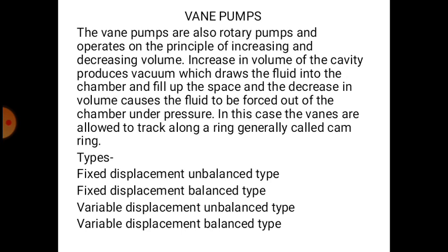So in gear pump, as the gears are unmeshing, at that time volume increases, and at the inlet side unmeshing is going to happen and it is going to suck the oil inside it, and at the exit port the gears are meshing and volume is decreasing, and the oil is forcibly discharged out of the pump. So volume going to increase, suction is going to take place. As volume goes on decreasing, delivery of the oil is going to take place. So this is going to happen in all types of positive displacement pump.